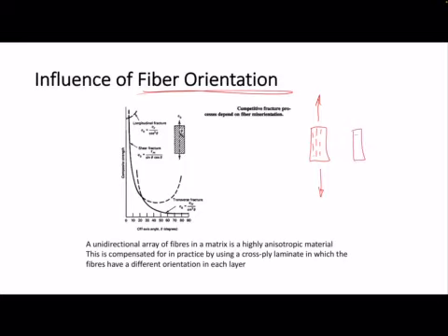If it is oriented like this, it's really not going to be strong. It's going to be more of a defect, and that's what we see. So on the X, we've got off-axis angle. So if it's 0, it goes up, it's high. If it goes to 90 degrees, it goes very low. So on this side, it's your composite strength. So very important how you orientate it.